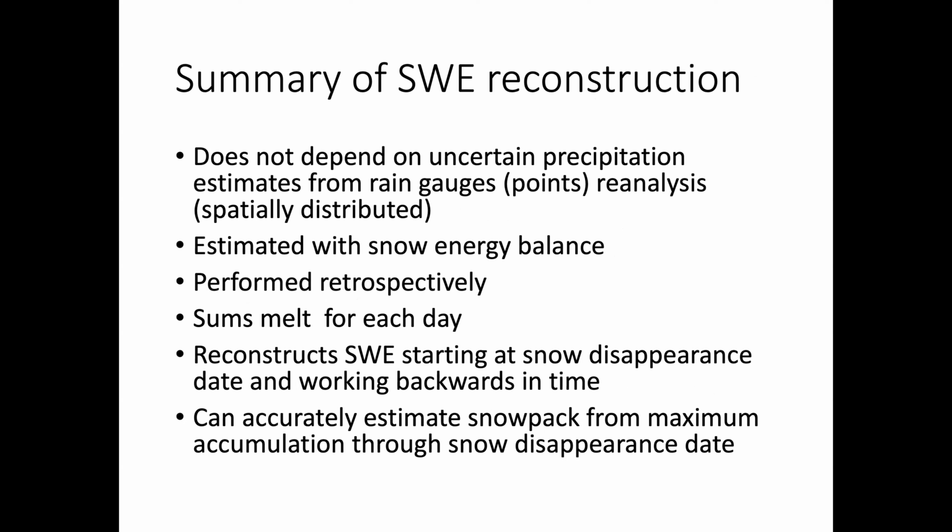The summary of Reconstruction. The reason we do Reconstruction is because it does not depend on uncertain precipitation estimates from either rain gauges, which are points, or reanalysis, spatially distributed data. We estimate the SWE and the melt with the snow energy balance. The Reconstruction is performed only retrospectively and sums the melt for each day. It reconstructs SWE starting at the snow disappearance date and working backwards in time. And it can accurately estimate the snowpack from maximum accumulation through the snow disappearance date.